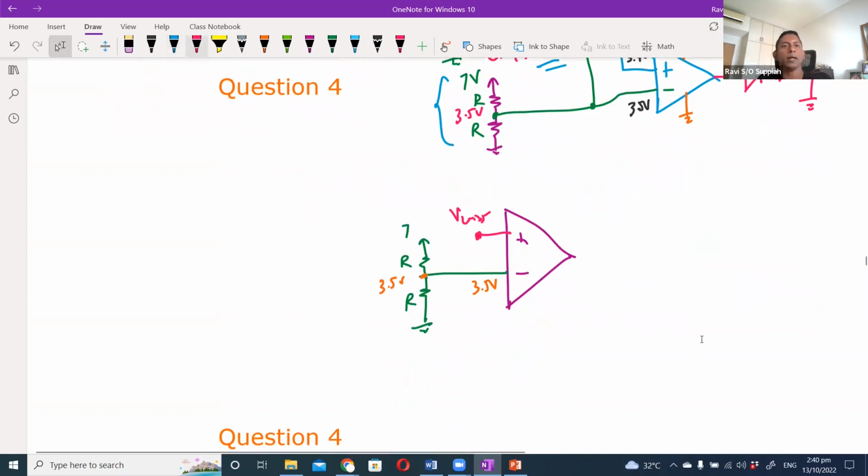Okay, so as before, if let's say this voltage is 3.6 volt, then I want the red LED to light up because it is bigger than the reference. So to make the red LED light up, I'll connect it this way.